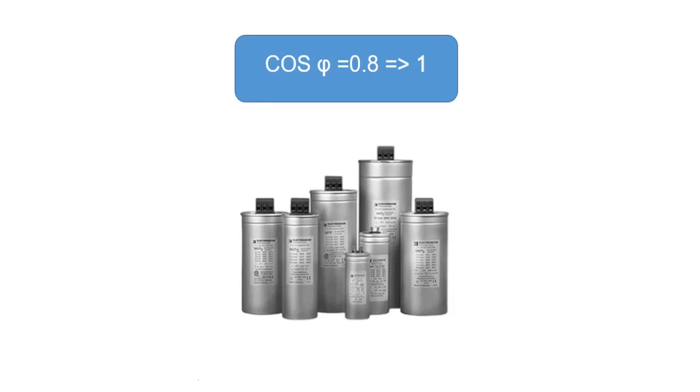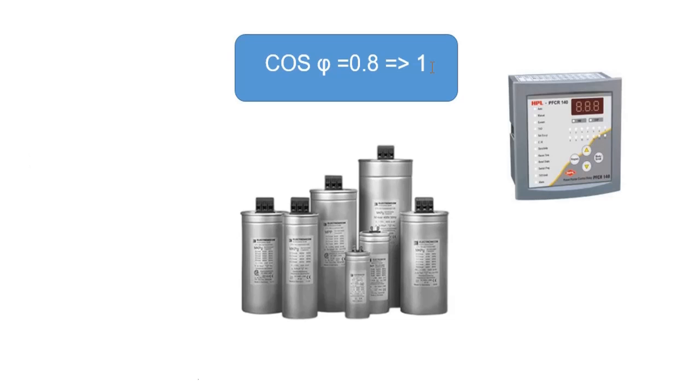Similar to building a warehouse, in reality the factory adds capacitors. The target is cosφ near 1, because less or greater than 1 is not good. They use a device to read it, and automatically balance the cosφ, like this.